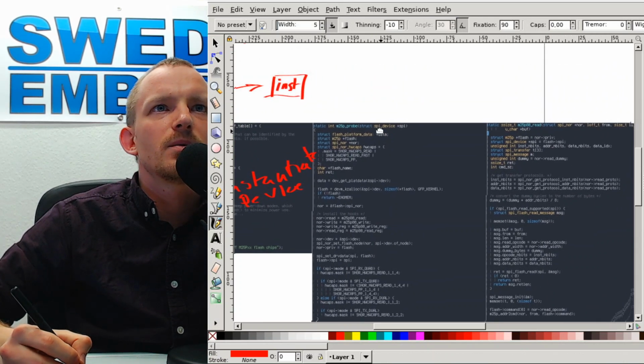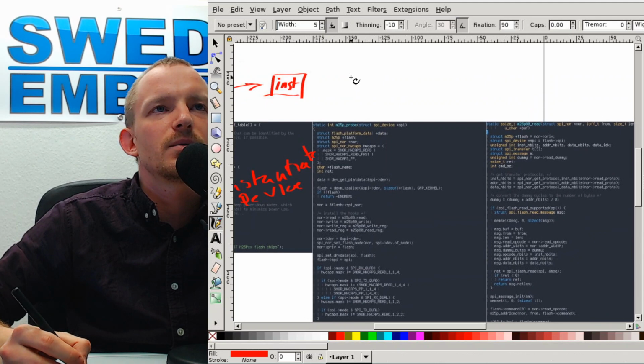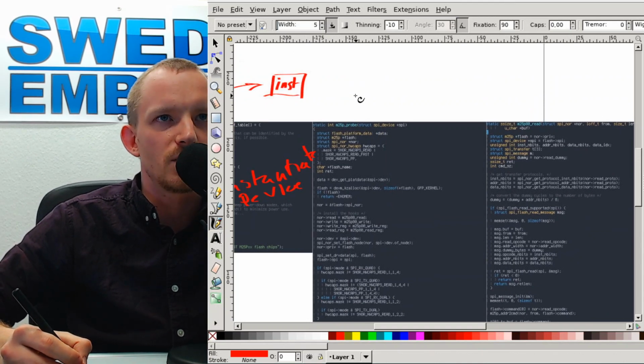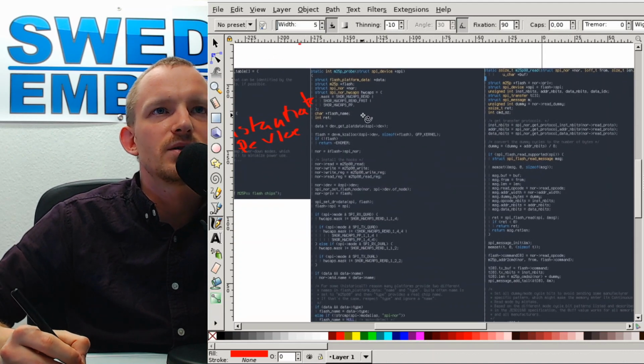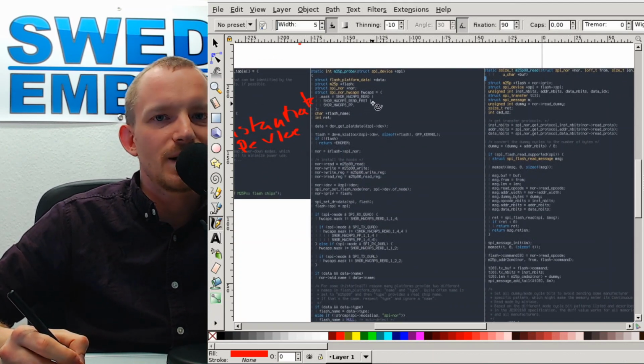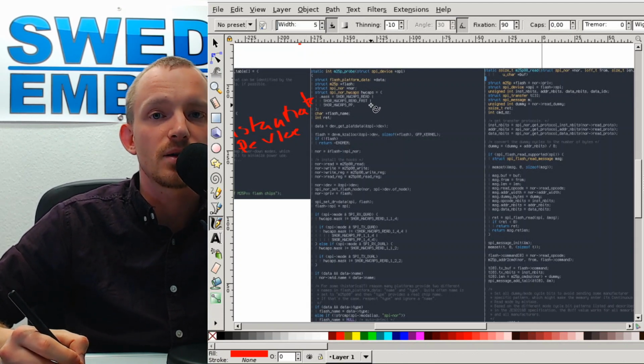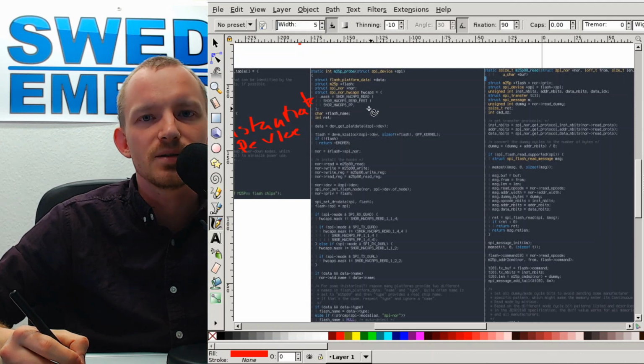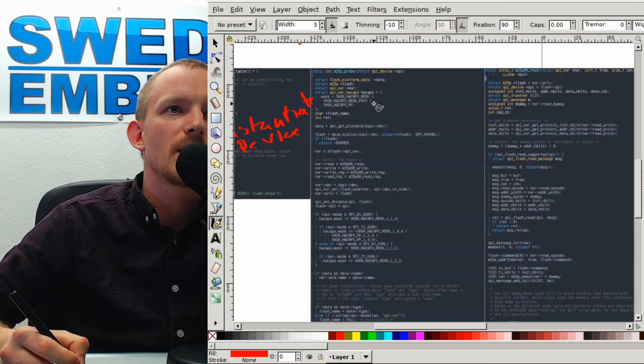So now we have the device tree node, and it's compatible. Now the probe method is called. The purpose of the probe method is to see if we can actually initialize the device. If the device cannot be initialized, then the probe method is not going to register an instance of this device with the memory subsystem, in this case, because we are creating an MTD device, a memory technology device.